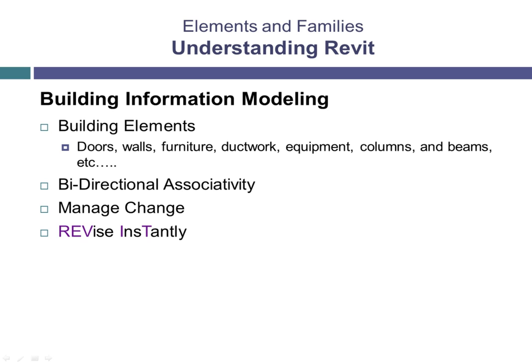Revit is a parametric modeler, driving geometric change from information supplied by the designer. For instance, a single door style can have many sizes, materials, and even types of hardware. Revit creates these differences with user-entered parameters, making a single graphic element flexible and consistent in different situations.